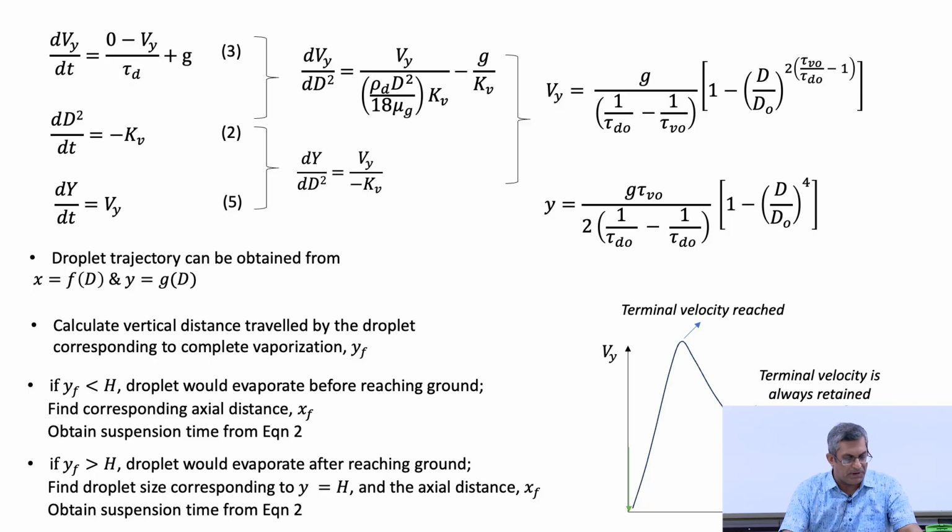Okay, so for that purpose, we can discretize the transport equations. And for simplicity, we can assume explicit finite difference method. So like this, for example, if you have the momentum equation, you can express this using finite difference method. Okay, so you can consider, let's say, forward scheme.